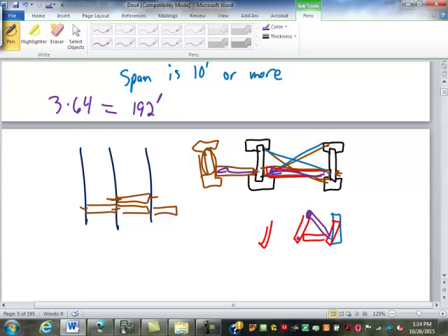Like I said, each joist has some resistance to that twisting. The X bracing transfers that load right up to that joint between the floor and the joist, and it should stop it there. It doesn't transfer any further. So the X bracing is isolating the load on each joist, so each joist is actually braced. I think the X bracing is stronger. It's just a pain. It's more time consuming to install. Very much so.